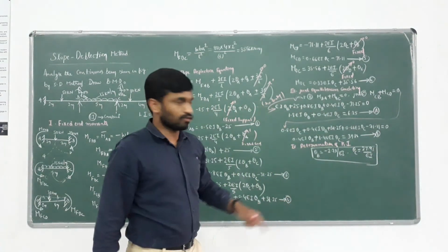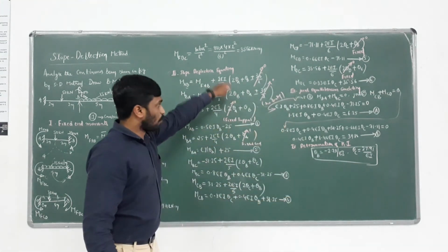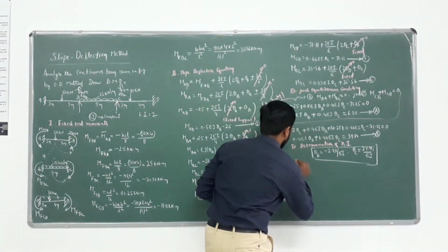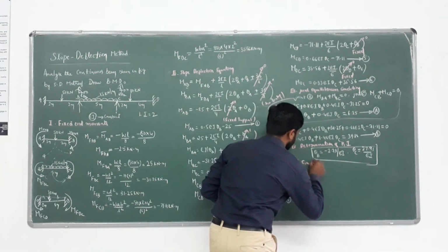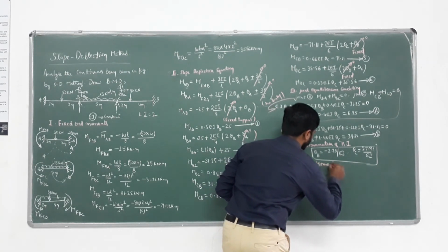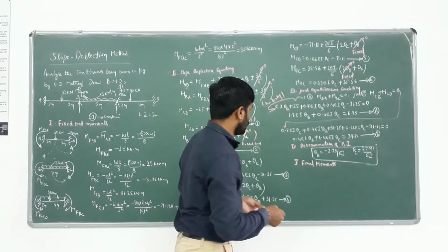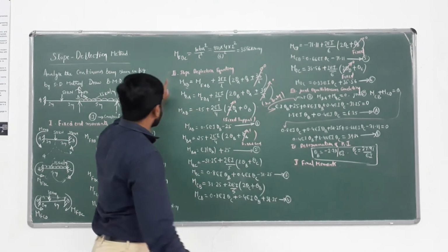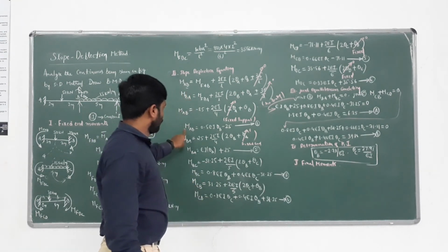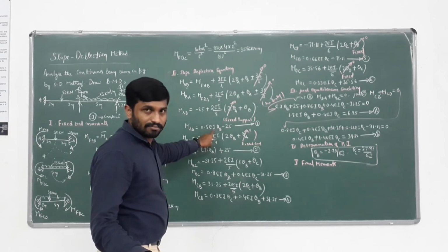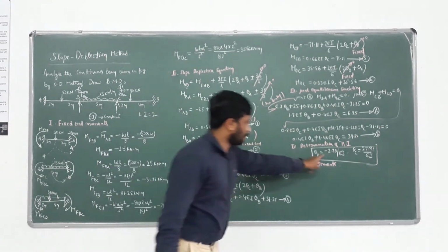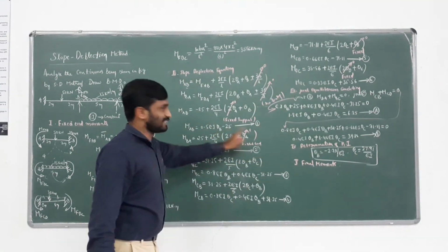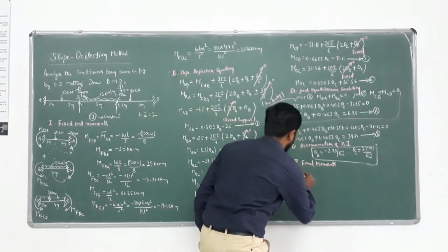These are kinematic indeterminates. Now substitute these two values in equations 1 to 6 for final moments. The last step, fifth step. Now substitute theta B, theta C in equation 1 to equation 6. I'll say an example. Equation 1, MAB, 0.5 EI into theta B, which is minus 2.73 by EI. EI will get cancelled. 0.5 into minus 2.73 minus 25, you are getting MAB.